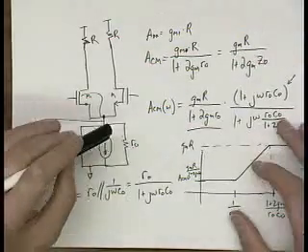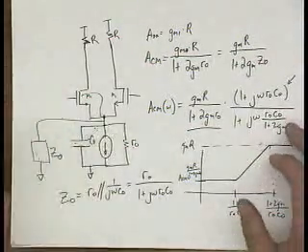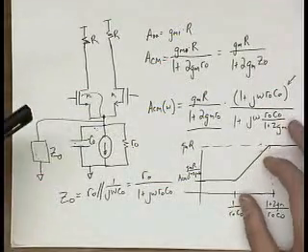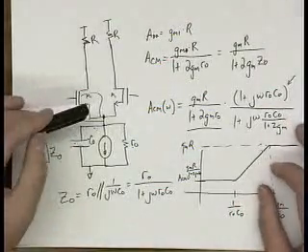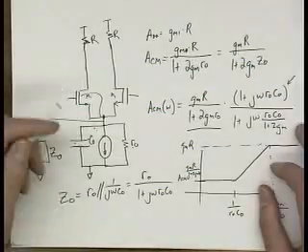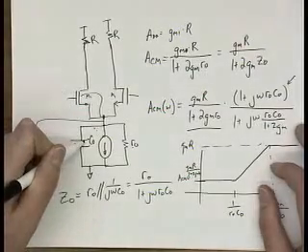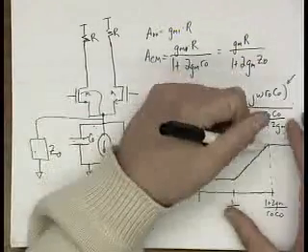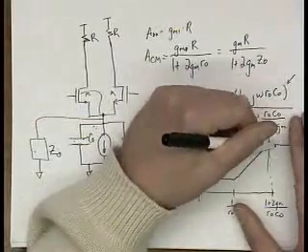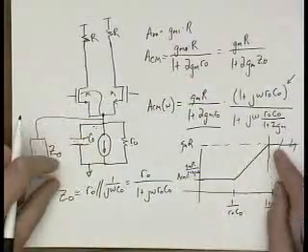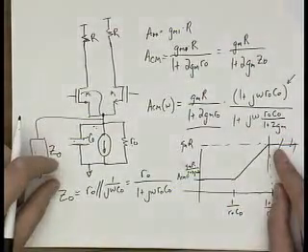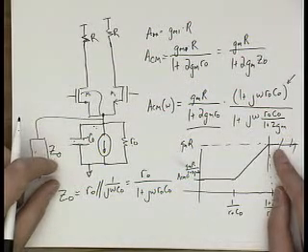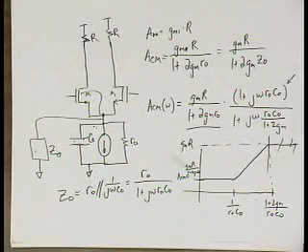Intuitively, it really depends on how, okay, so now let's talk trade-offs. How important is it? Well, what you need to figure out is how big this capacitance is. Because at high frequency, forget about up here, because if you're all the way up here, then your common mode gain is equal to your differential mode gain. Therefore, you failed spec categorically.